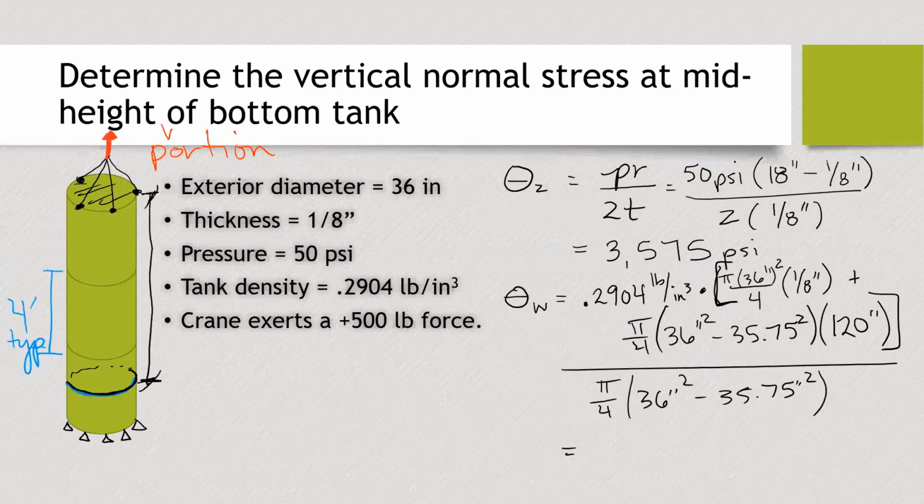So you have the density times the volume, right? Yes. Then you multiply by gravity to get force. No, because this density is written in terms of pounds per inches cubed, so it's already in force units. But you're right, sometimes density is in terms of mass, and then you would need to multiply by g.